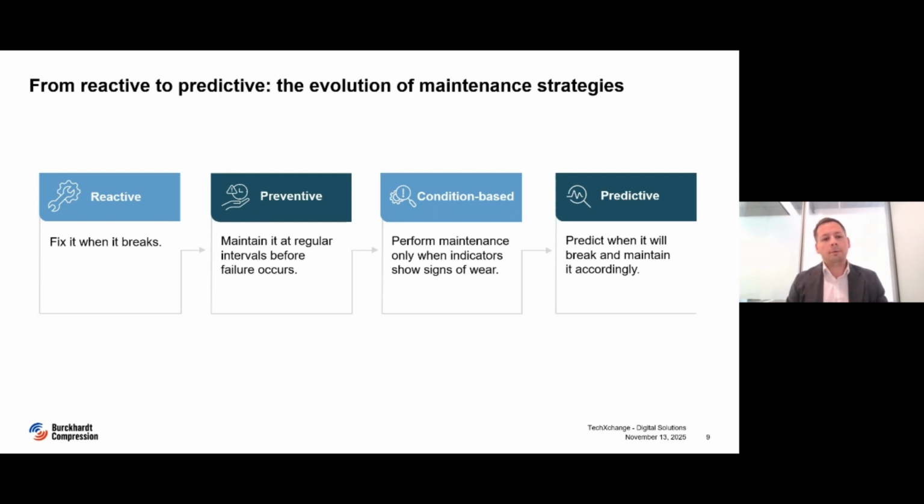On the other extremity, we have preventive maintenance. That is when a compressor asset is maintained at a fixed interval of time. This approach is very useful for certain types of failures, especially those which have predictable development in time, such as failure modes of sealing components, for example, or valves. However, it's not universal, and some failure modes are actually not addressed by this approach.